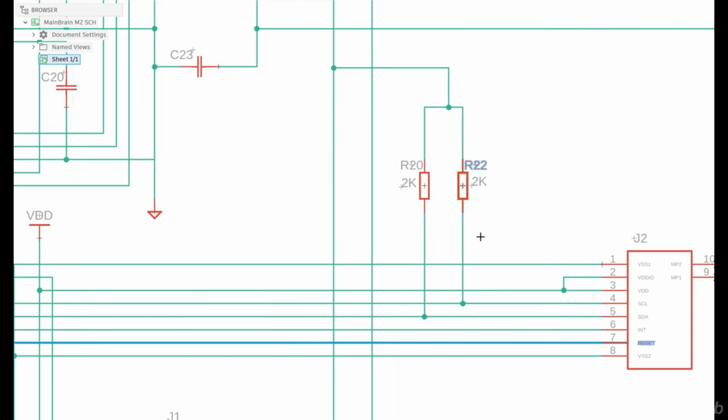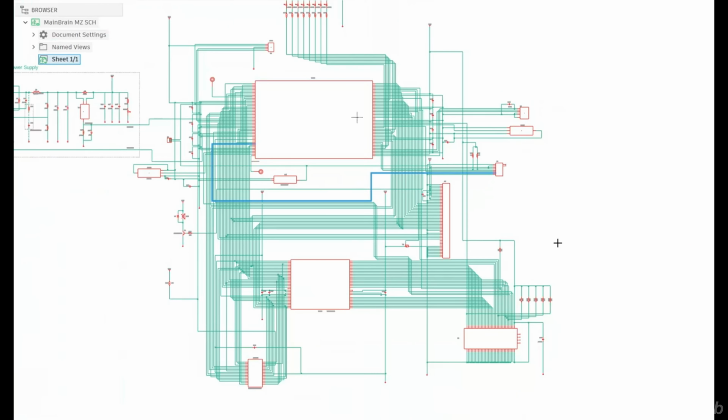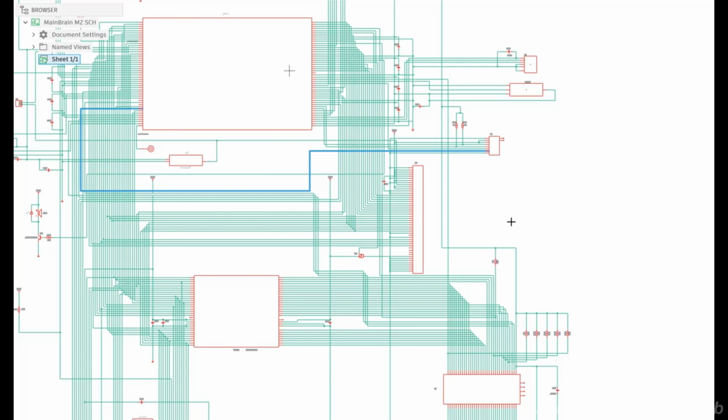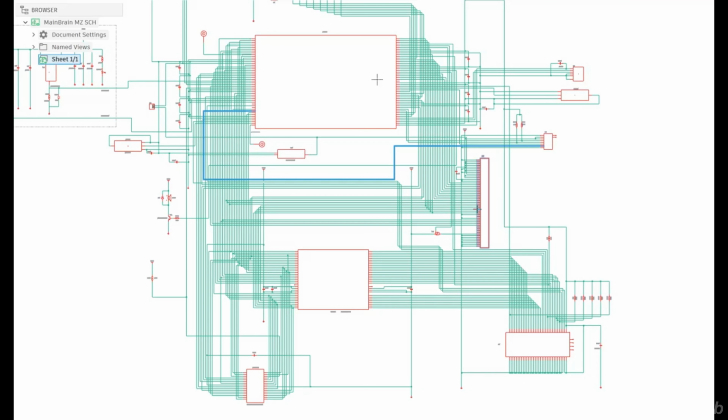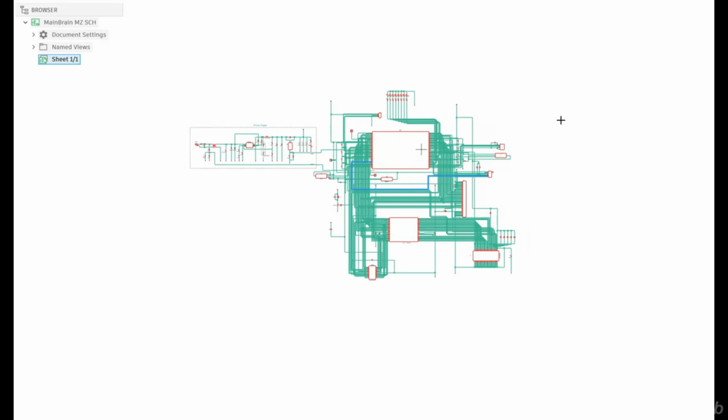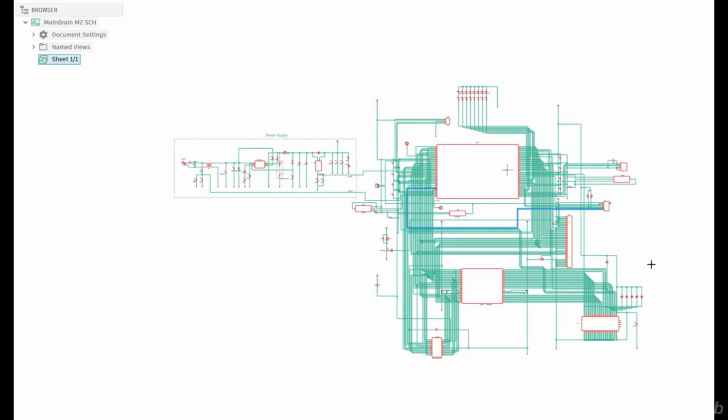And then, to be within specification of the I2C, we have 2 pull-ups like we discussed in the I2C video. And so those are the 3 interfaces for the display: the display interface, the touch interface, and the backlight interface. All right, 3 sections that we have to program. We have to write driver code for each of those 3 sections.